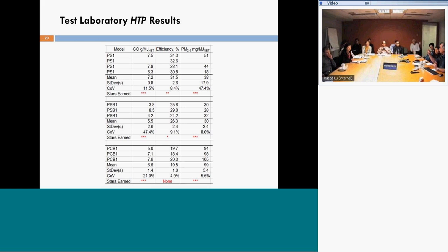That's the top figure. How much work would that get to be able to use for cooking? The bottom number is the fuel consumed to reproduce the burn cycle, carefully defined as the following. It's the fuel needed to replicate the burn cycle in a series of identical replications, not the first one, because people take wood off the fire and put it in the next fire, and we look for that. So if there's wood left over that's going to be reused, use it in the next fire because that's what people do. Bits of coal left over which are not used are thrown away and are counted as consumed.